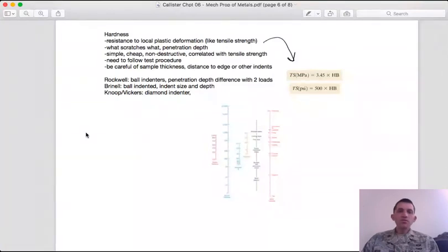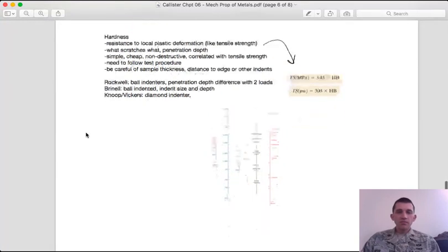So it's pretty useful to be able to measure mechanical properties of materials, but it's destructive, right? You have to break the material in order to get any information about its material properties, which I suppose is fine if you are characterizing an entire class of materials or doing materials research. But if you just want to measure a particular part non-destructively, tensile testing is not really the best tool. A much better one is to measure the hardness.